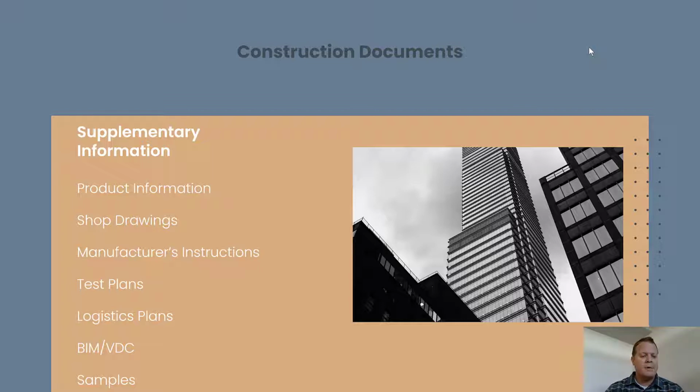But then you have BIM and VDC, and I keep using BIM as synonymous with VDC. And I know there's some nuances, BIM being the term that's a little bit older, VDC being the more current term. People understand it, but it's virtual design construction or building information modeling. And so we're talking about doing supplementary drawings to the design drawings and the specifications showing how the building's going to function, how the different components are going to come together, coordinating space, things like that.